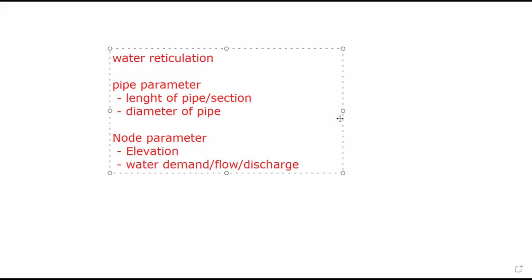We'll still come to that in detail, but many of us have only seen detailed work. You see a pipeline, they will draw the diameter of the pipe using the diameter sign, theta. They will put the elevation for you there. They will put the slope in terms of percentage, maybe they say 0.5%. Then they put the elevation of point A, elevation of point B. So we're all coming to that. But I want us to know that these are the 4 parameters you need.